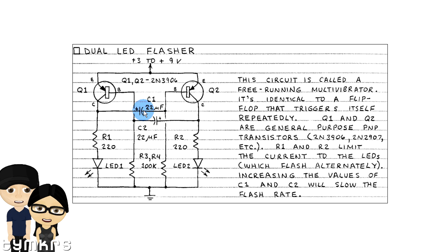These capacitors allow AC voltage through, which will cause the opposite base of the transistor to go up to a higher voltage, high enough to override the emitter voltage, and once VB is greater than VE, this transistor will turn off. When this turns off, the capacitor will discharge through the LED down to ground, and then you start it up again. So I'll show you guys a simulation that we did to demonstrate this a little better.